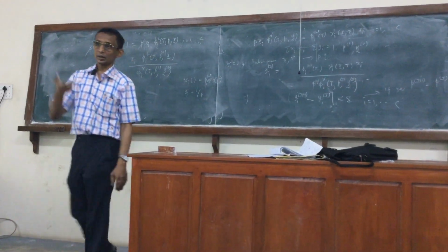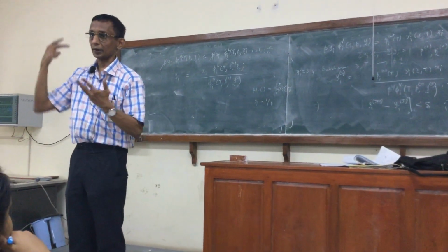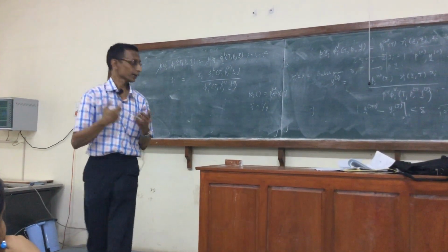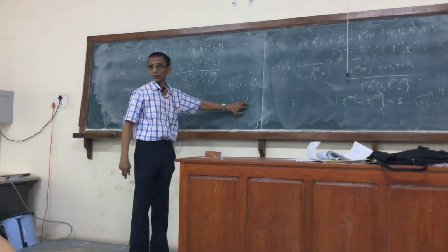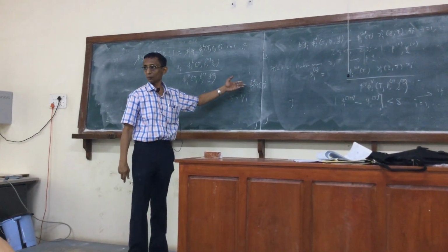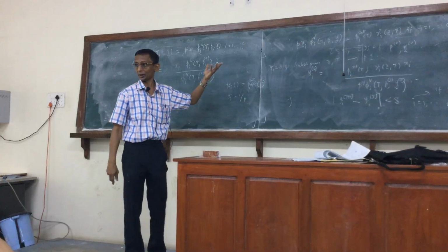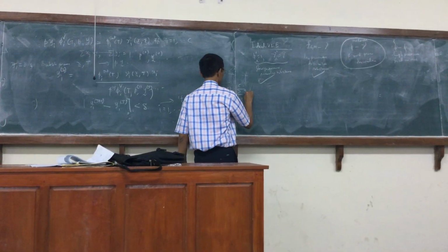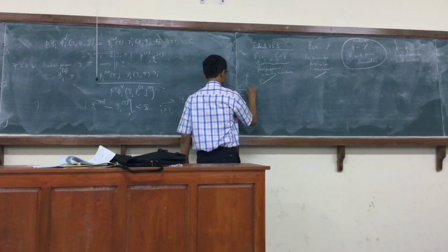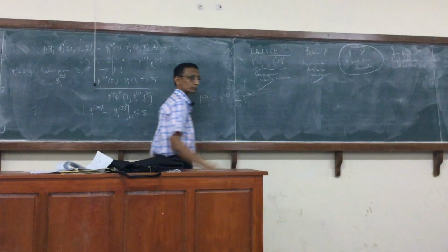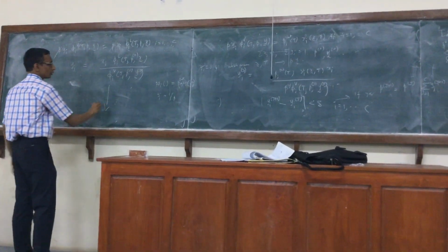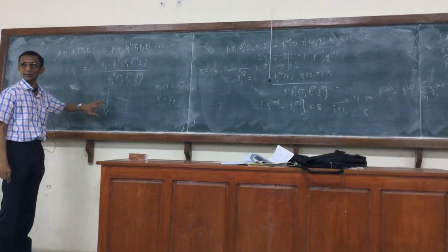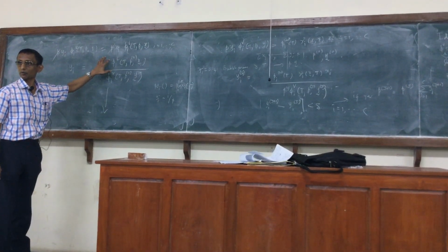So that means if the yi add up to something greater than 1, I have chosen a lower pressure than what I should have, so I have to increase the pressure. With that idea, I can simply say that this has to be the sum over j equal to 1 to C of yi at j plus 1. Now the same thing will apply here. Only this equation is different. That part of the algorithm remains the same for bubble pressure.